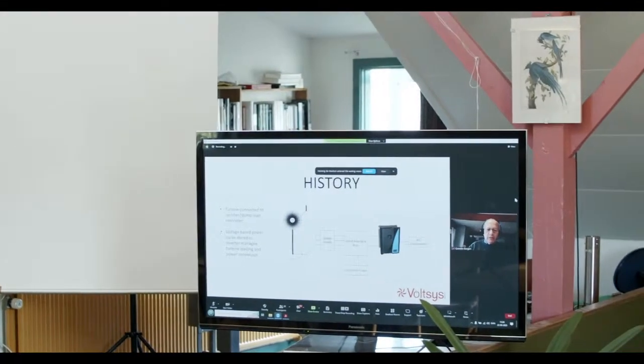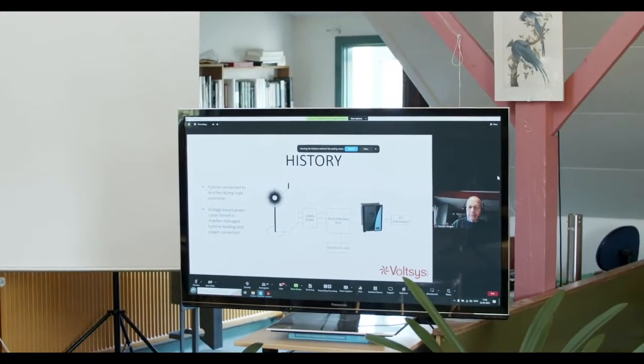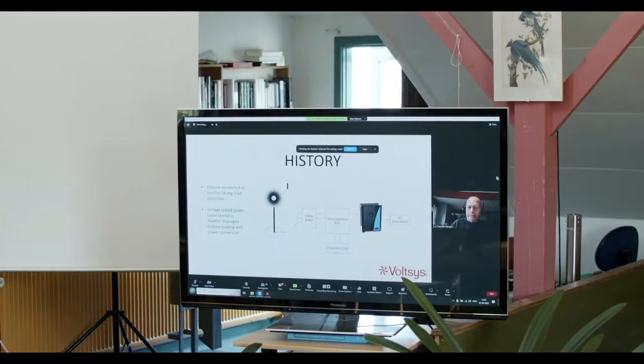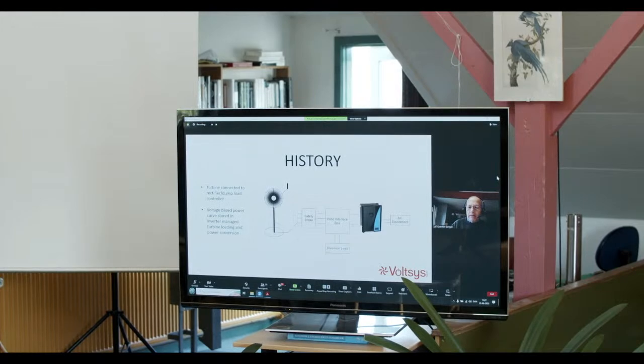You had a turbine connected via a safety brake, a short circuit brake, to a wind interface which provided rectification, and this went into wind inverters, which typically were made by either SMA, Jinlong, or Power One in Italy. The early models only worked on the basis of having a power curve based on voltage to control the conversion.